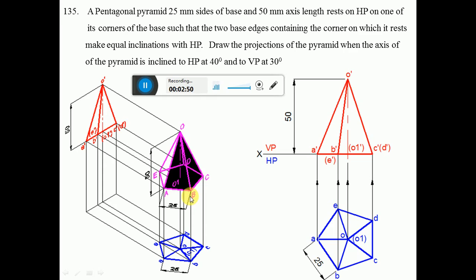So now we need to see how to draw this in an orthographic view. In order to draw it, consider a vertical line of a distance of 25 mm. As explained previously, you mark the points C and D. From C you measure an angle of 108 degrees included angle and draw a line. Similarly, from the point D you measure an angle of 108 degrees included angle by using the protractor, and then you draw a line.